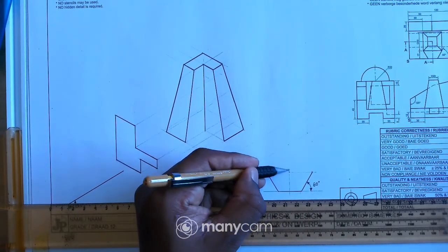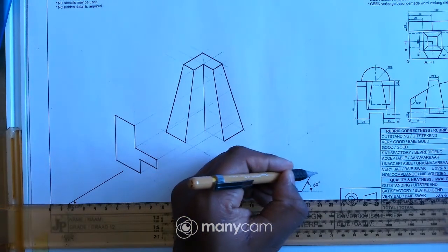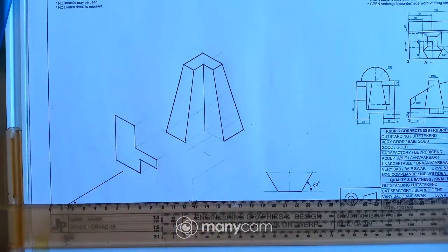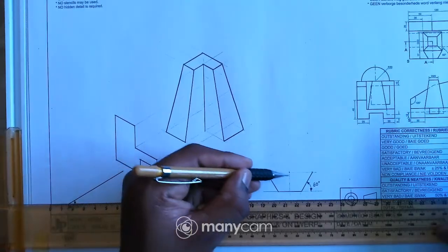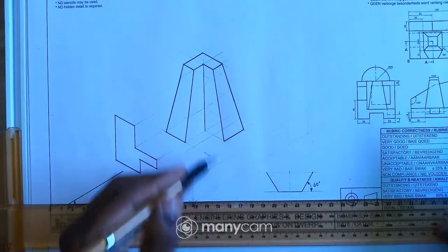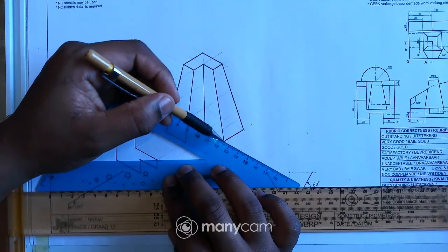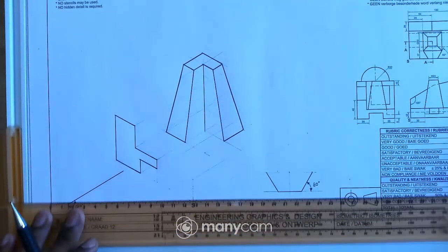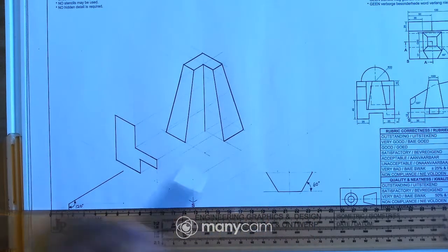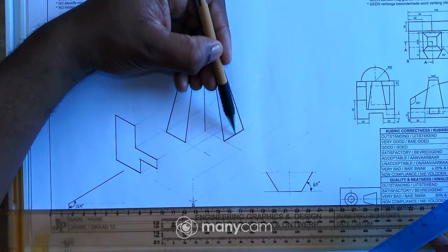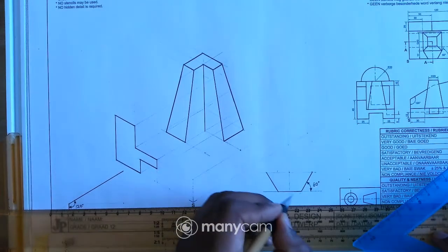Okay, so now it's time for us to place this auxiliary view on our isometric drawing. So now obviously I must first get these center lines on our isometric drawing, and then we can just place the auxiliary view. So now for this center line, where is it on our drawing? That center line is right here. I can just extend this line to there. So this is the center line, which is this one. And then what about this one? We do have the center line, it's this line, right? Okay, so now I do have this point. This point is this one, right?